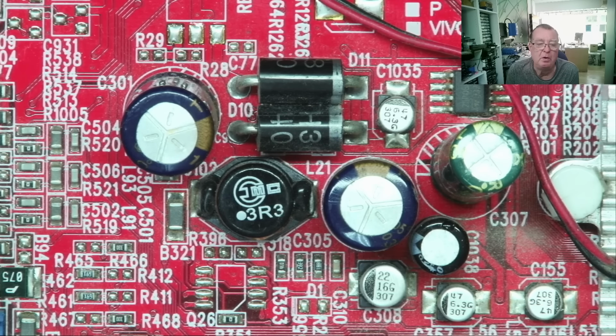The problem was the formulas that were stolen were not complete. Some parts or compounds, chemicals in there, were missing. So those capacitors, after a period of years, failed. And this is, as I mentioned, known as the capacitor plague. So yes, in a certain age of electronics, you will find faulty electrolytic capacitors is a major problem, but outside of that era, not really.